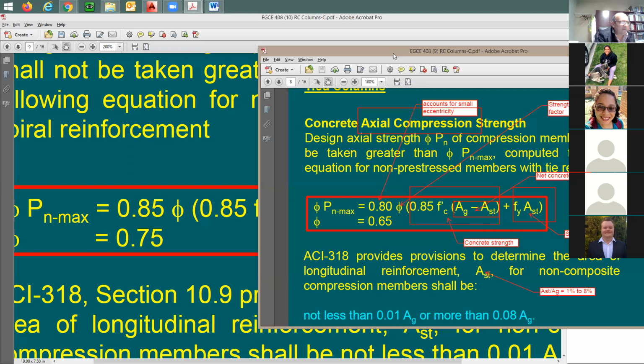I mean, we understand that the spiral column is going to be stronger. Roughly by how much? I'm going to go with about 15%, possibly. How did you come up with this ratio? Because the strength of confined concrete is, like you said, about 10%, 15%. Okay.